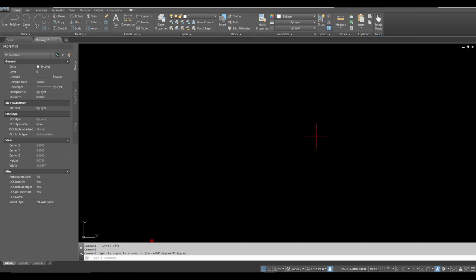Okay. One more thing in this hefty preamble here. If you're using a newer version of AutoCAD, like I think it's around 2018 or newer, you're going to have this thing called Intelligent Update enabled by default. And what Intelligent Update does is it limits AutoCAD's effective frame rate to eliminate overhead on your PC.